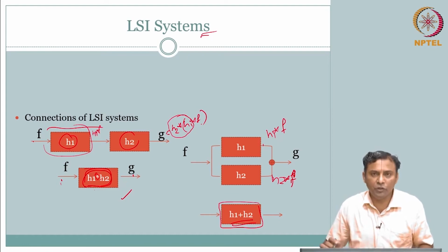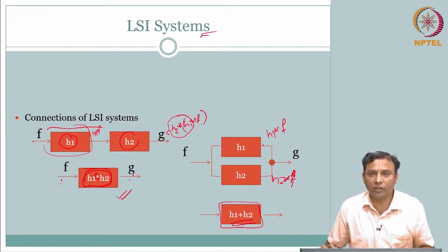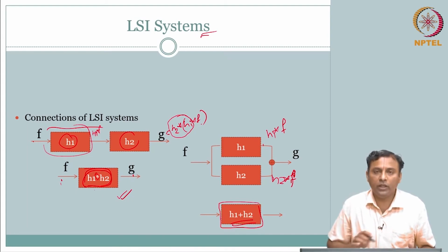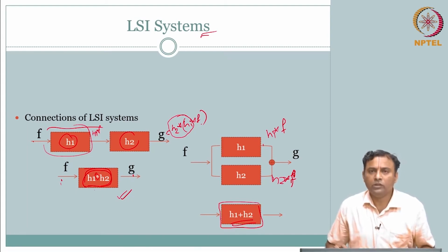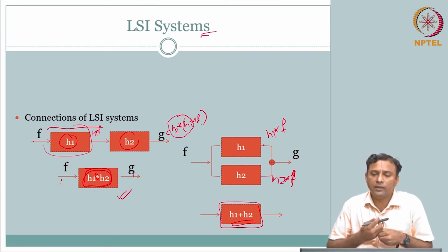So, we could use the convolution property, and we talked about the system transfer function concept, the system impulse response, the point spread function. How do you use the system impulse response function that connects your input and output through the convolution operator? Clearly that is very intuitive and straightforward, but there are other operators through which we could still analyze the system properties.